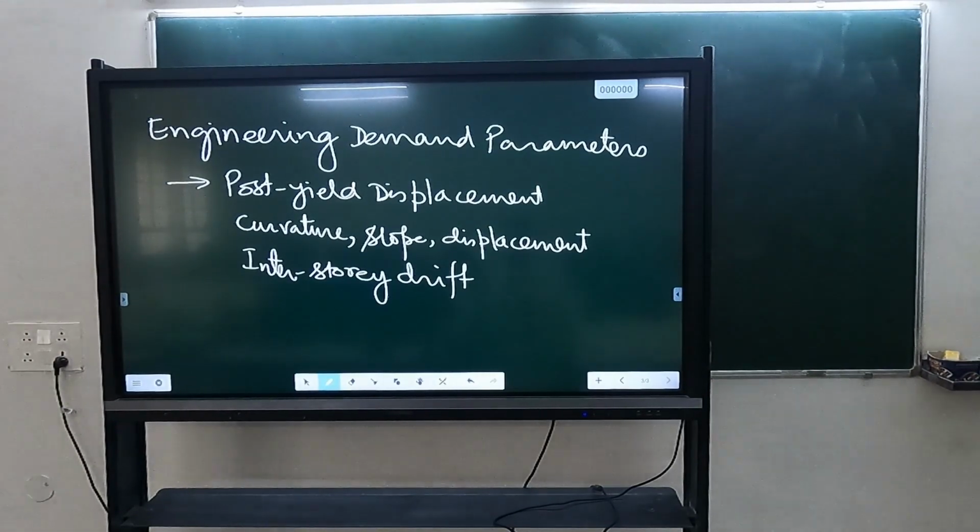When you think of non-structural components in a typical building, let us say a hospital building, what are the typical non-structural components which come to your mind? Infills, pipelines. Can we call infills non-structural? Are those structural or non-structural? You have studied the role of infills in frames. If there are embedded partitions, we can say those are non-structural elements. Infills are non-structural in the sense that the safety of the building does not depend on them. If the infill collapses, the building is not going to collapse.